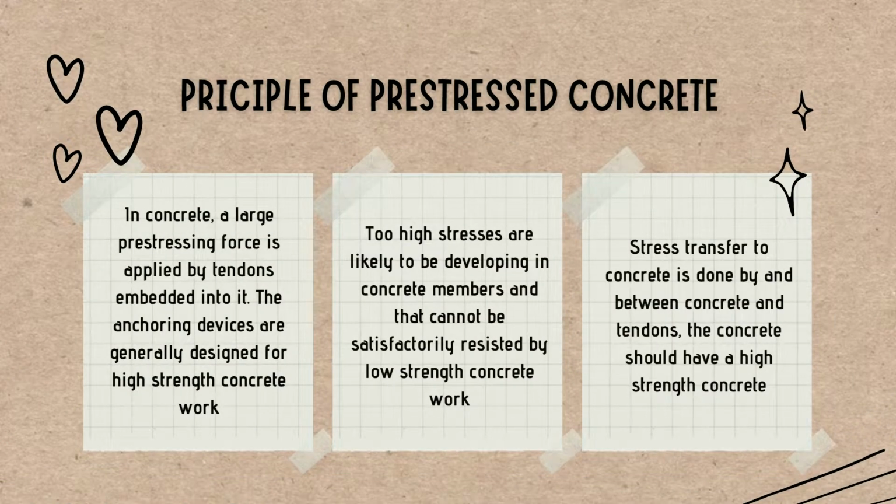Principle of prestressed concrete. In concrete, a large prestressing force is applied by tendons embedded into it. The anchoring devices are generally designed for high-strength concrete work. Too high stresses are likely to develop in concrete members and that cannot be satisfactorily resisted by low-strength concrete work.